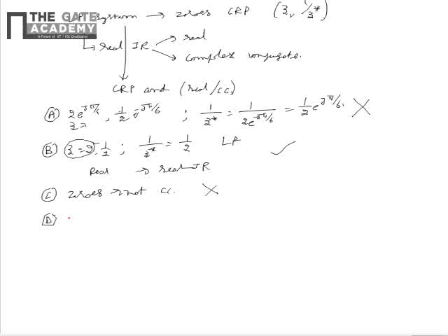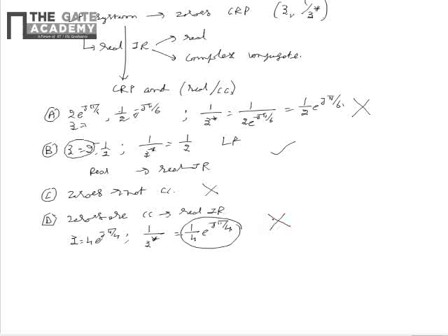Similarly, if we consider option D, in this case also we see that the zeros are conjugates, so the impulse response will be real. But if there is a zero located at 4e^(jπ/4), we expect another zero at 1/z*, which boils down to ¼e^(jπ/4). But there is no zero located at ¼e^(jπ/4). Hence we can say that the system is not linear phase. Hence this is also not a correct option.